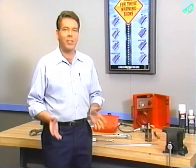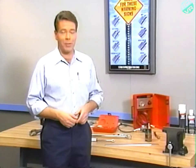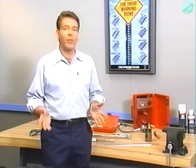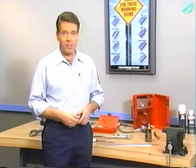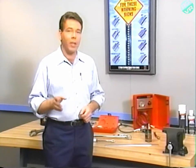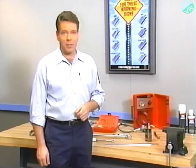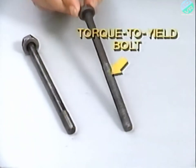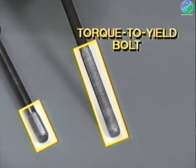The last section in our Back to Basics look at engine service concerns torquing procedures. Many engines now use torque-to-yield bolts, which must be tightened in a special sequence. One way to tell if the engine you're working on has torque-to-yield bolts is by a visual inspection. Torque-to-yield bolts have a thread depth roughly twice that of a regular bolt. It's important never to mix regular bolts with torque-to-yield bolts.